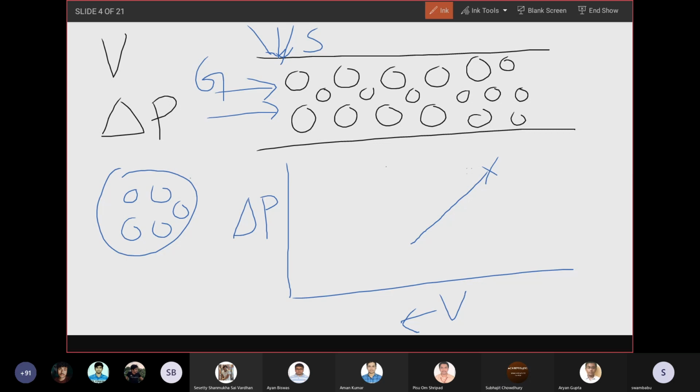And why is the particle floating, dispersing? Because of the buoyancy offered by the air. When you reduce the velocity of air, the buoyancy will also reduce, and the drag will also reduce. Hence, the dispersion will be reduced. So at this state, these are the particles, uniform. As you reduce velocity, the particles tend to come close. Still, some amount of dispersion is possible, but the uniformity will be reduced.